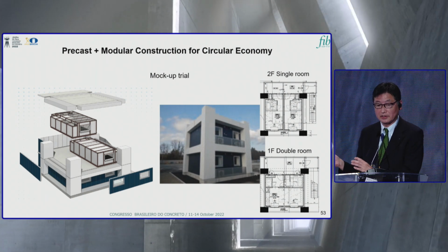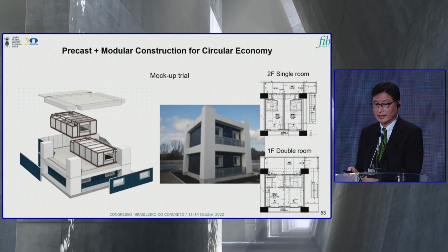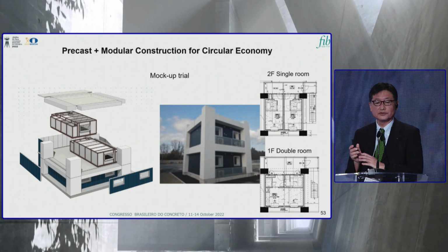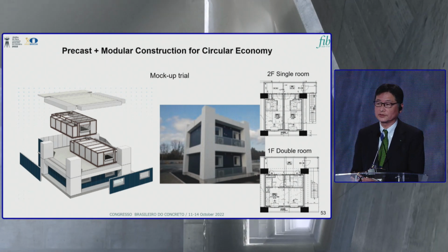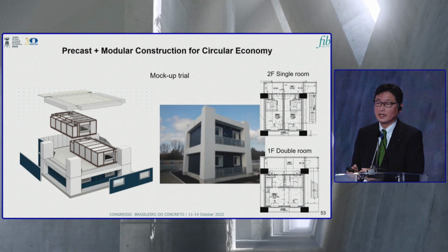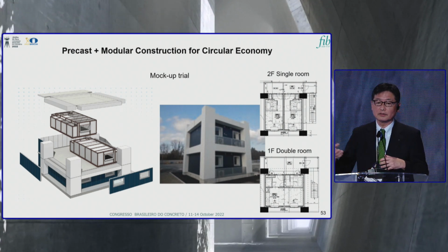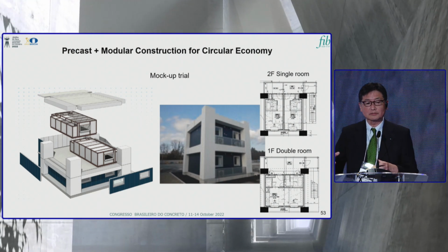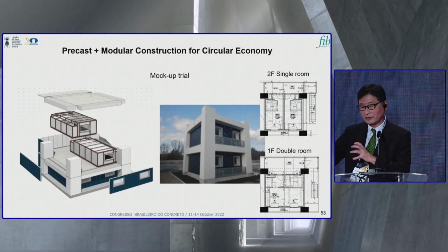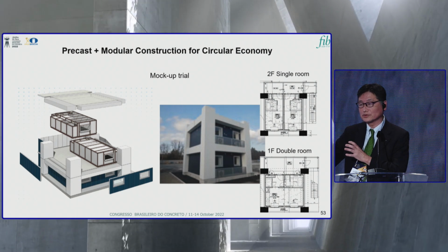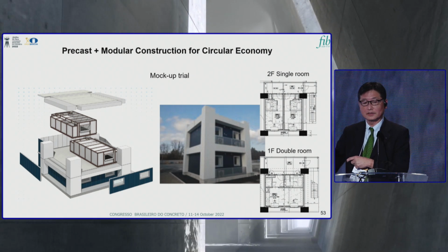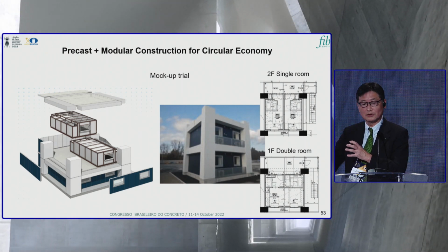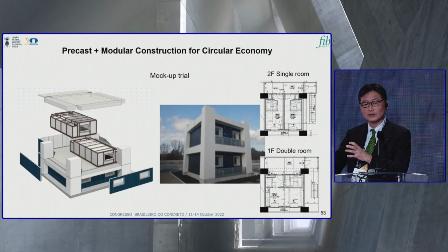But this is a reinforced concrete structure. And for this new technique, we should confirm many things, such as precision and transportation from more than 300 kilometers. During transportation by trailer, the room has torsion, and after arriving at the site, the room has some residual torsional deformation.